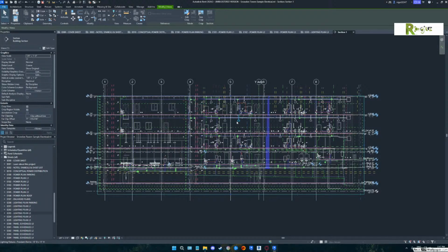See, in other words, if I'm doing a structural file, when I teach you to do structural drawings, we're not going to set up a level line for the 3rd floor to be at the same location as the architect is, because we want to go to the top of the steel, not to the top of the concrete deck, because that's how they generally work, the top of steel. Okay. So a structural level lines should usually be 5.5, 6.5, whatever the slab thickness size is.